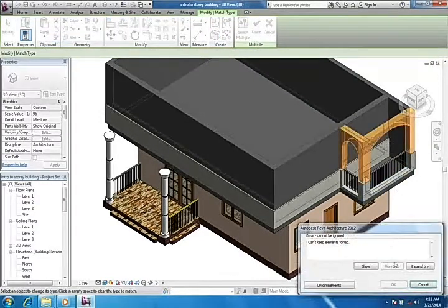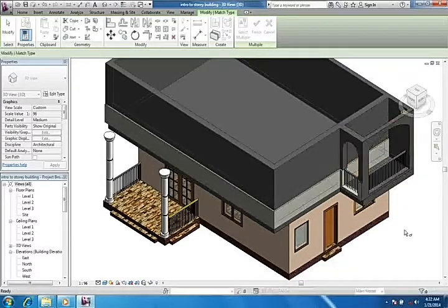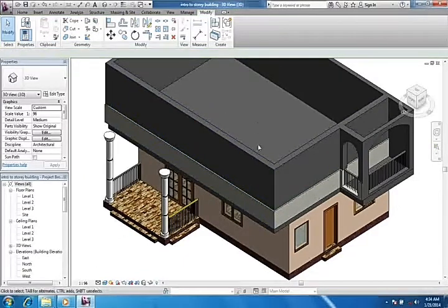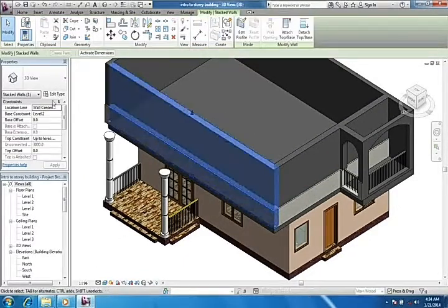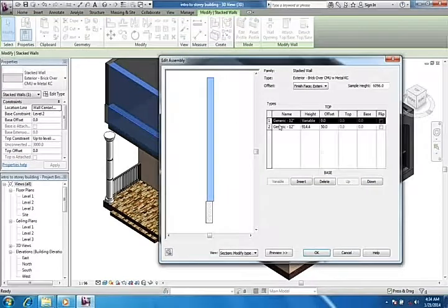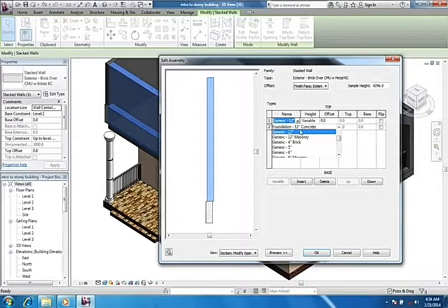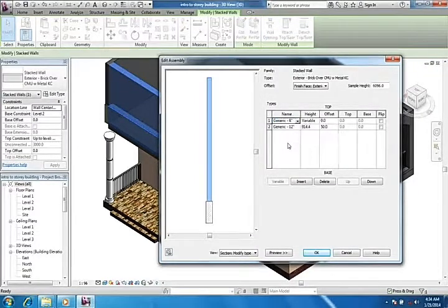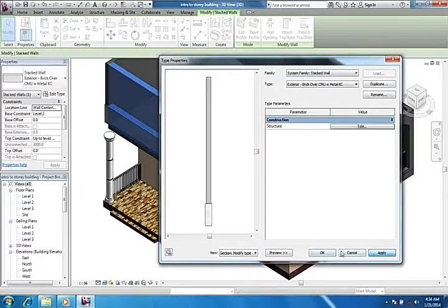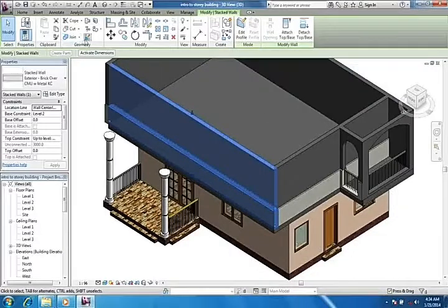So this time around, okay, I'm still having an issue here. Let me cancel here. So folks, I'll go back to the editing. Quickly I'll change the thickness of the upper part to be 8 inches. I think that one will be better, and say OK, apply, OK.